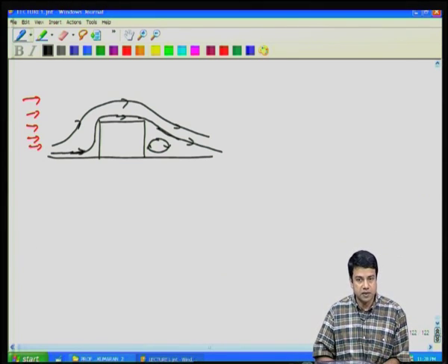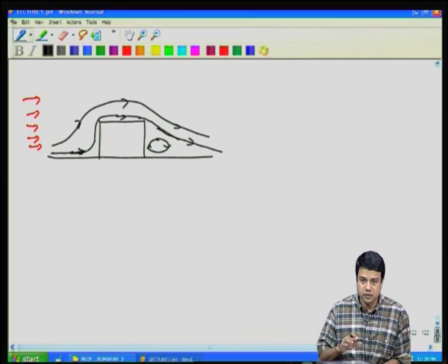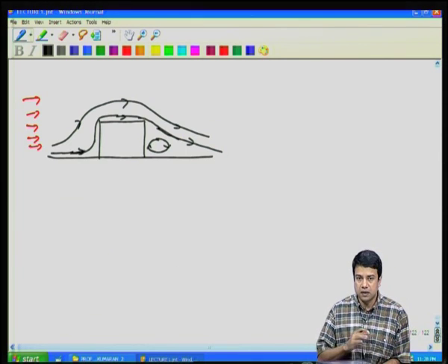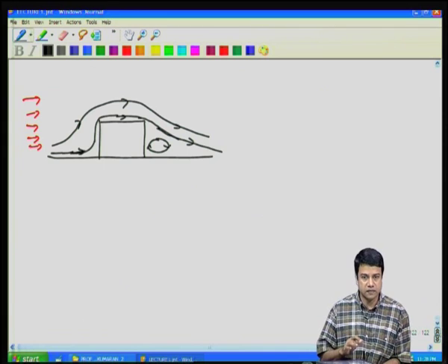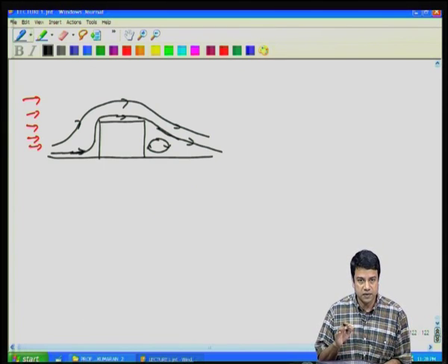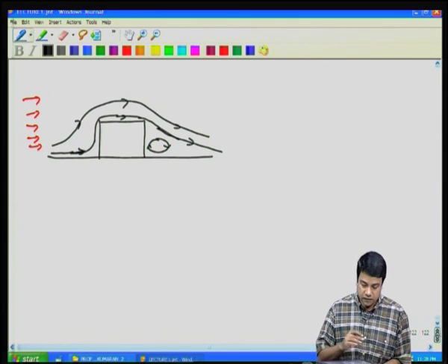This is not what happens at low Reynolds number when we neglect inertia. The reason is that this is inconsistent with the idea of reversibility and linearity. I told you that when the direction of the velocity at the boundaries is reversed, the direction of the velocity at each point within the fluid is also reversed. And this is not a reversible flow.